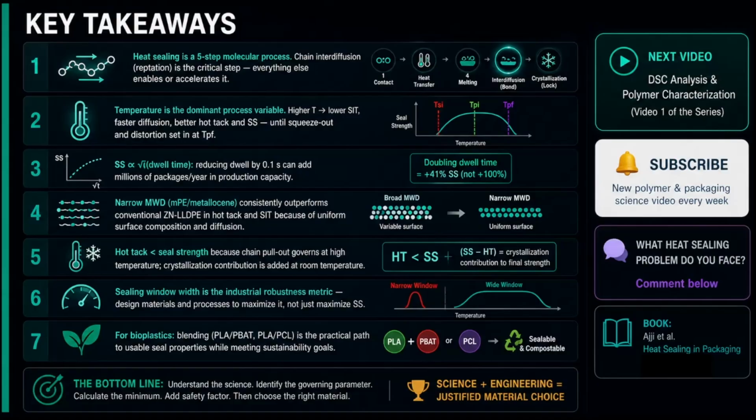3. Seal strength scales with the square root of dwell time, not linearly. Doubling dwell time gives 41% more strength and costs you production rate. Know the trade-off. 4. Metallocene PE outperforms conventional LLDPE.